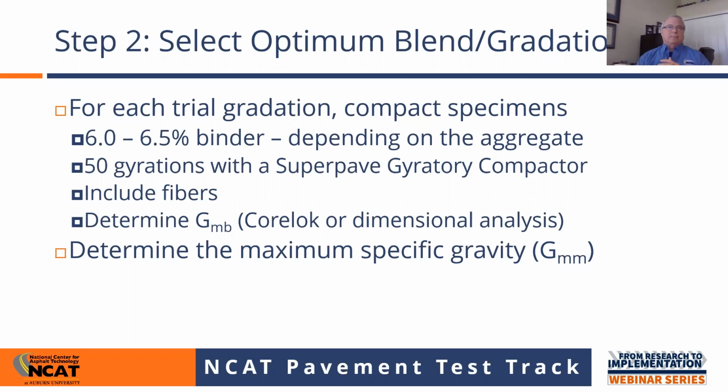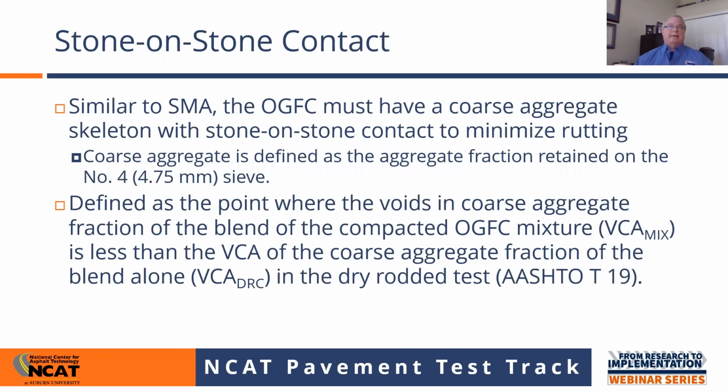Once we get those compacted, we'll determine the bulk specific gravity of the compacted specimen. Obviously you can't do the normal SSD test because it's so porous, so you either have to use a CoreLok device or dimensional analysis. I'm sure you could probably use paraffin coating or parafilm if those still exist, but most people do it with the CoreLok or dimensional analysis. And then you take uncompacted mixture and determine the maximum specific gravity.